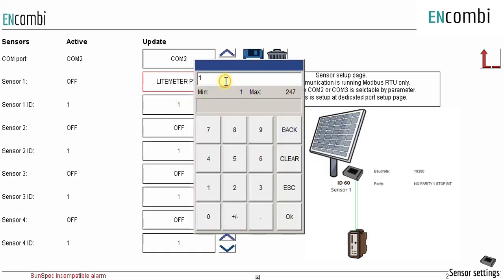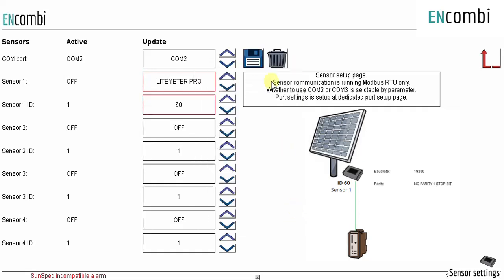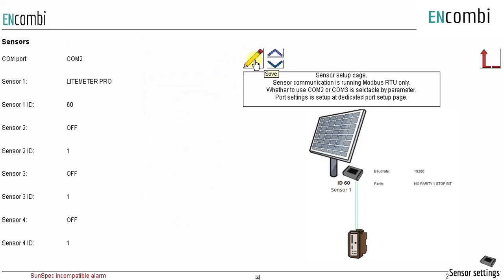Finally you have to enter the ID number of the sensor, which is the sensor address for ECPV2. Then save your settings. Here you have selected sensor 1 for all 3 parameter readings. Once you have completed this setting, the POA, BOM and ambient temperature readings will be available under the monitoring.